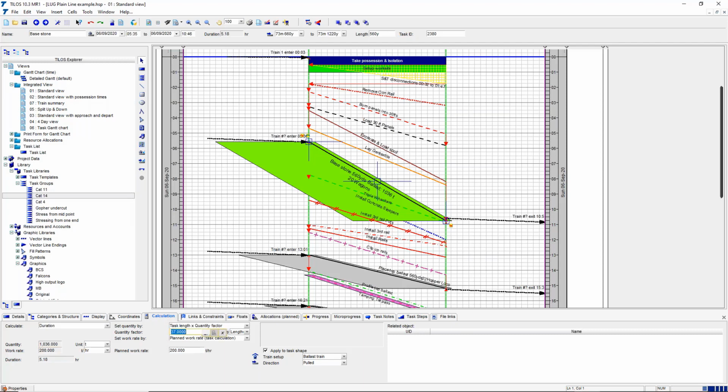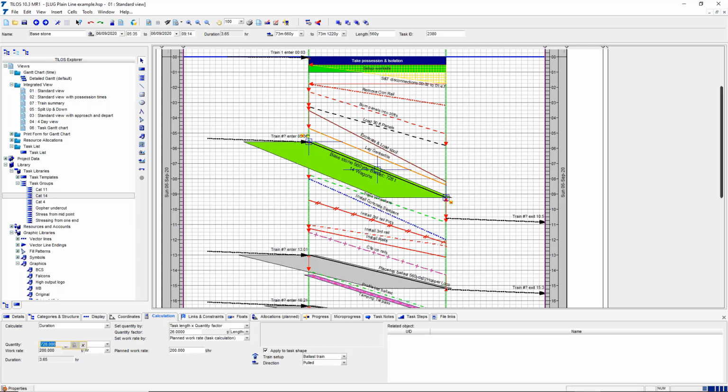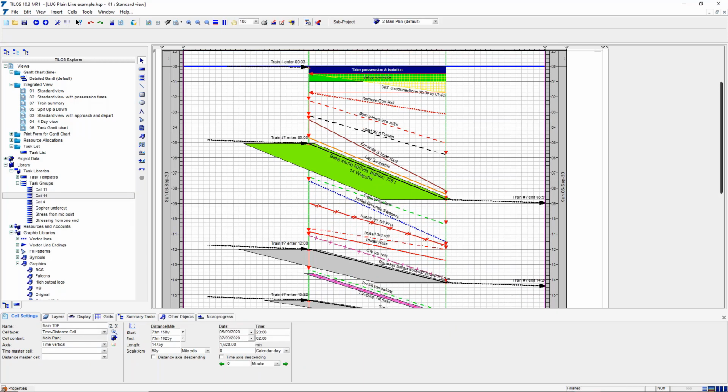it's a special calculation tool that the industry uses if it's got curves, and they say how many tons per distance, in this case a length. So if we say, well, there's only 26 in our ballast calculator result, so that is then going to reduce the total quantity of material to be excavated, and it means we need fewer wagons, and so the length of the train is shorter, and that's got a massive impact on when the following operations can start, and we can calculate the whole thing.